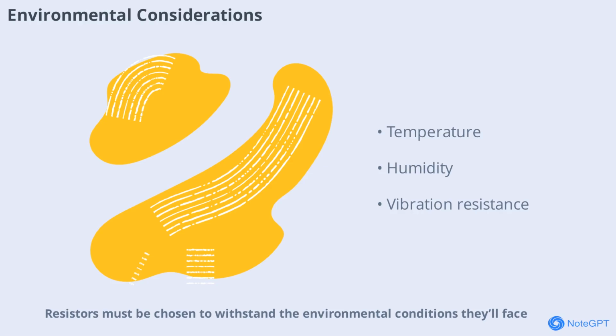Resistors must be chosen to withstand the environmental conditions they'll face, such as temperature, humidity, and vibration. Special resistors are available for harsh environments, ensuring long-term reliability and performance. Always consider the operating environment when designing circuits.